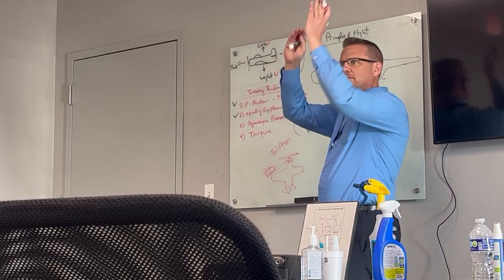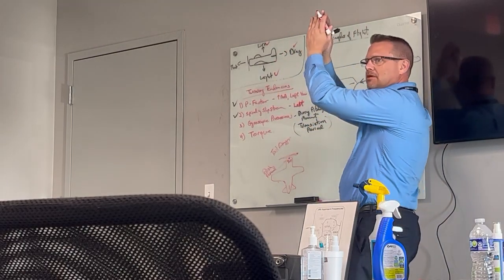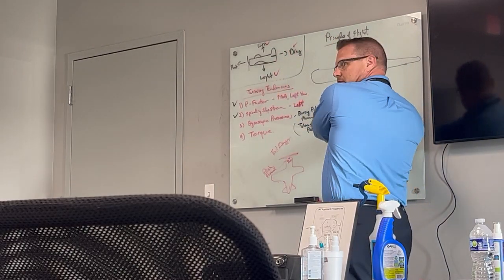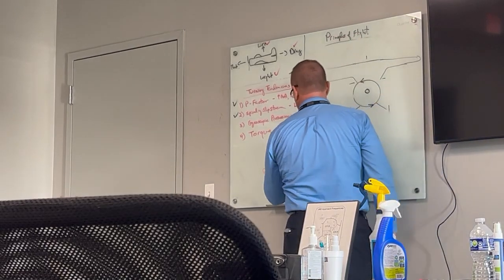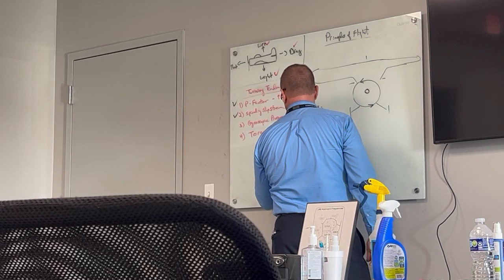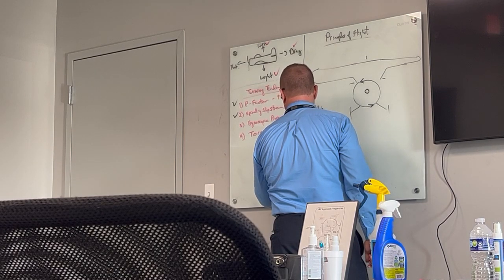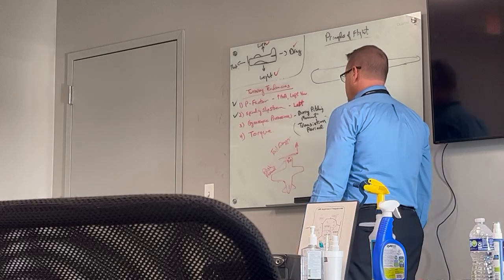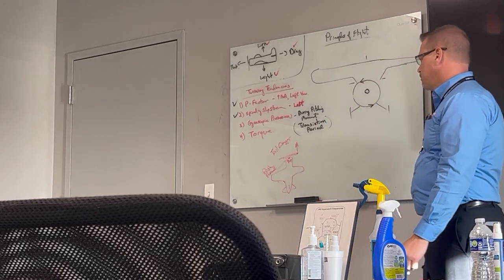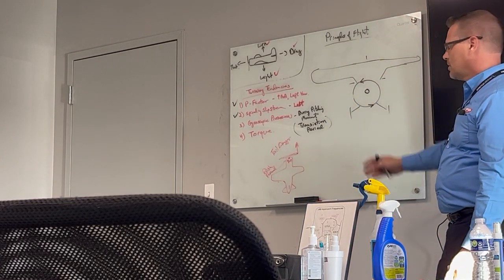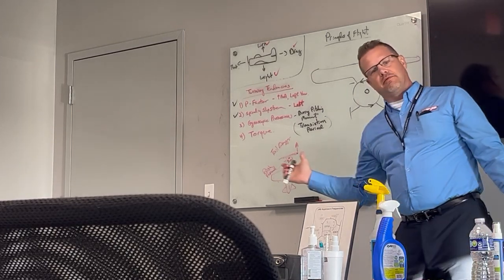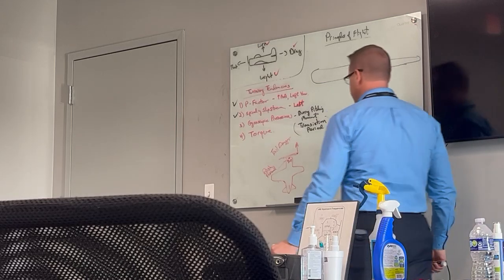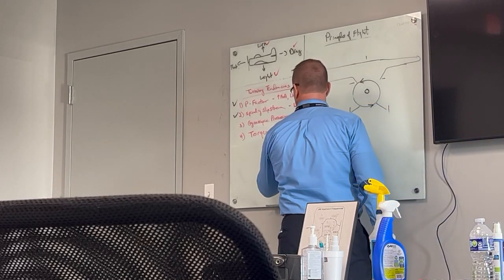Because the blade is spinning from, if it's at top dead center and you're looking in the cockpit, where does the blade go? It goes this way, right? So it's felt to the right. So therefore, it's going to feel as though it's a yaw to the left, if you will, or that force is going to push hard from the right side, yawing our aircraft to the left. So that's gonna create, again, another yaw to the left.